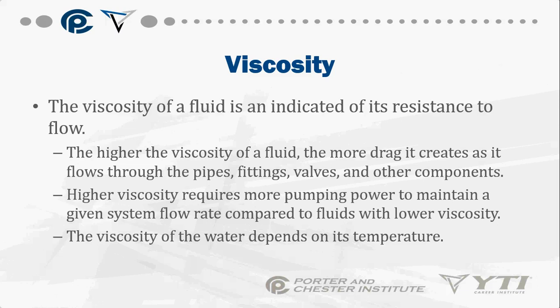Which is why you have, in some cases, that antifreeze glycol solution. Because if water starts to freeze, its density starts to change, right? So if it's starting to freeze, all of your components are going to have a harder time moving the water through. And when that happens, it starts to slow down, which is where you start having issues.